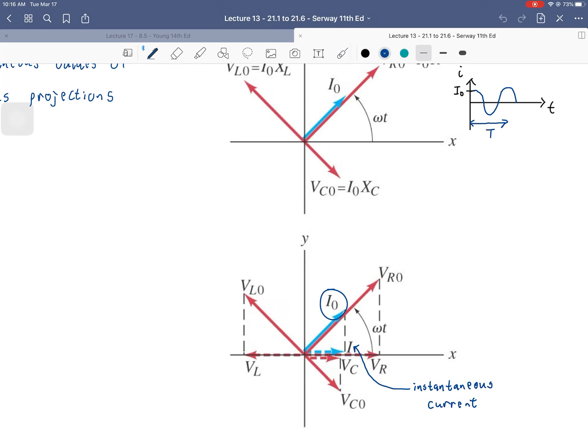So we see just the rotating current. And if that was just the rotating current, it wouldn't be all that helpful because it would certainly show directly that a sinusoidal function of a variable, in this case current, varying over time, goes through a unit circle like so, and that is consistent with this picture up here. But the real utility of the phasor is that now we can have our phase shifted voltage on the inductor, phase shifted voltage on the capacitor, combined with the unphase shifted voltage across the resistor, and take all three of those together and get the total effect of the voltages, and really see how all the vectors are moving together.